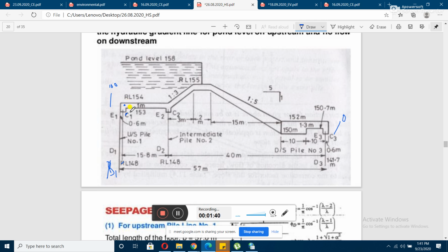So we have seen what the corrections are for this point. One is for the influence of this pile, and another is for the thickness of the floor, because you are finding out the pressure percentage at this point, right? But actually your pile starts from below the floor, just at the bottom fiber of your floor.